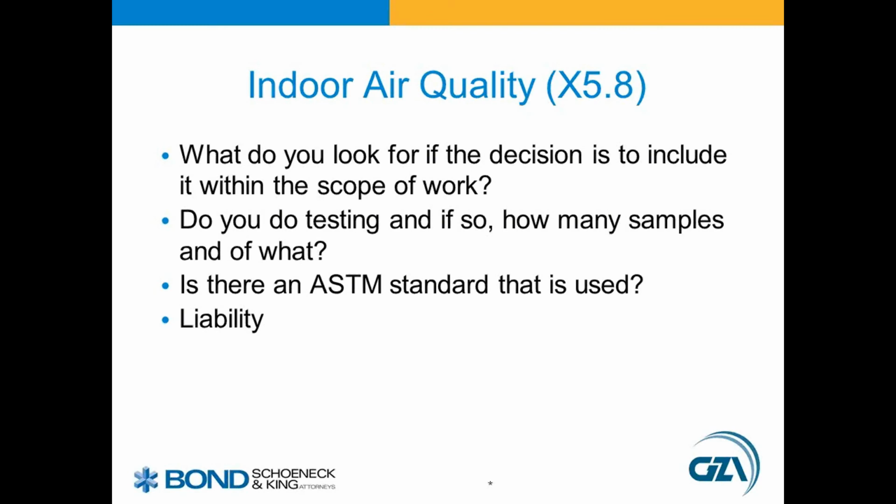If we're concerned about chemicals, the common method is EPA TO15, which essentially allows for an 8-hour collection of air into a vacuum cylinder with a regulator to collect air over that 8-hour period. That's then sent off to a lab. Results will be compared to OSHA levels, the permissible exposure limits, which are concentrations of specific chemicals in the air that OSHA has determined are not detrimental to the employee's health over an 8-hour period.